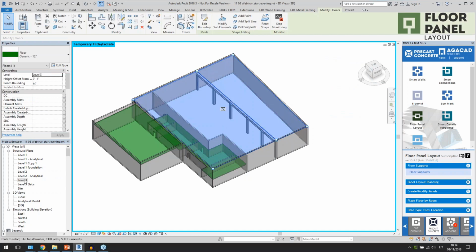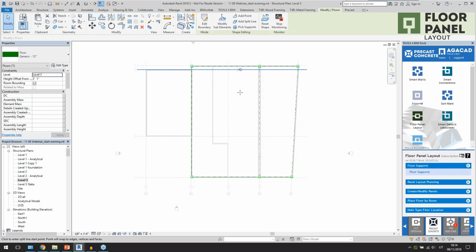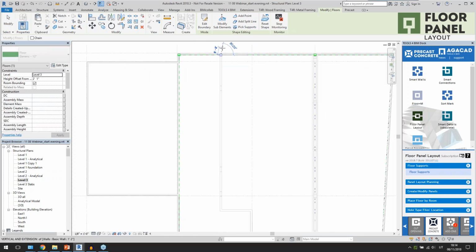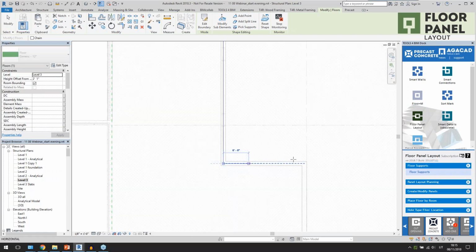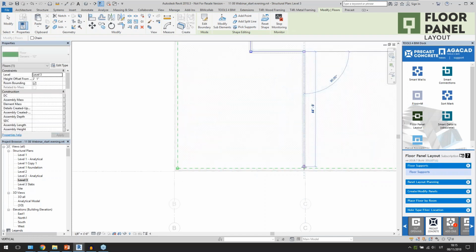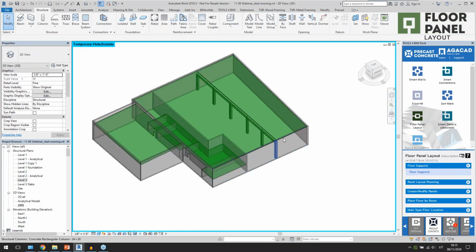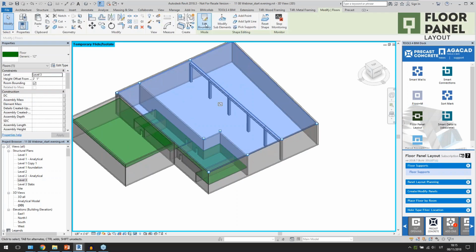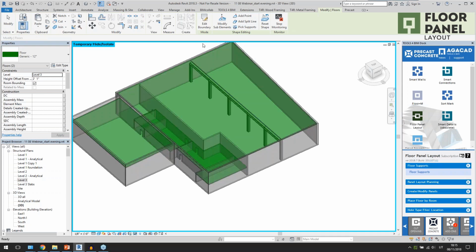And also, if you want to, you can just go to the plan view, for example, and just add a splitting line, anywhere you don't have supports, or maybe you have this kind of corner support, which is kind of easier for me to create like this and divide the floor into these kinds of regions. So you'll see now it looks like this. Modify. Yeah, so now I have these lines. They are all at the same level, I hope. Yeah, it looks like this.